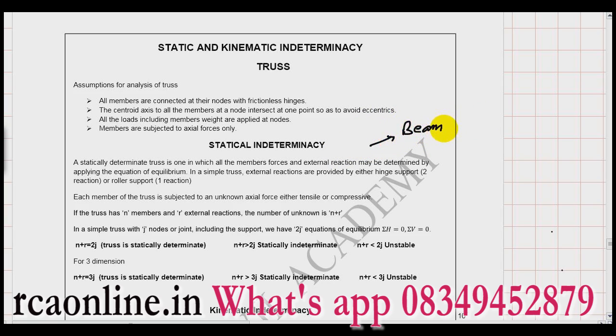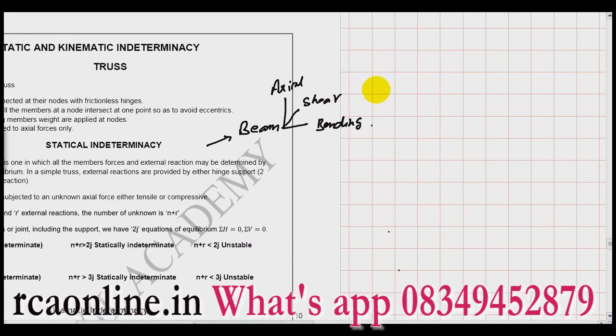So, what we learnt in beams is that there are three types of forces mainly, which are axial, shear and bending. So, in a beam we have three unknowns in one member. So, we can say the total number of unknowns is 3m. Then we have R reactions. So, total unknowns become 3m plus R.